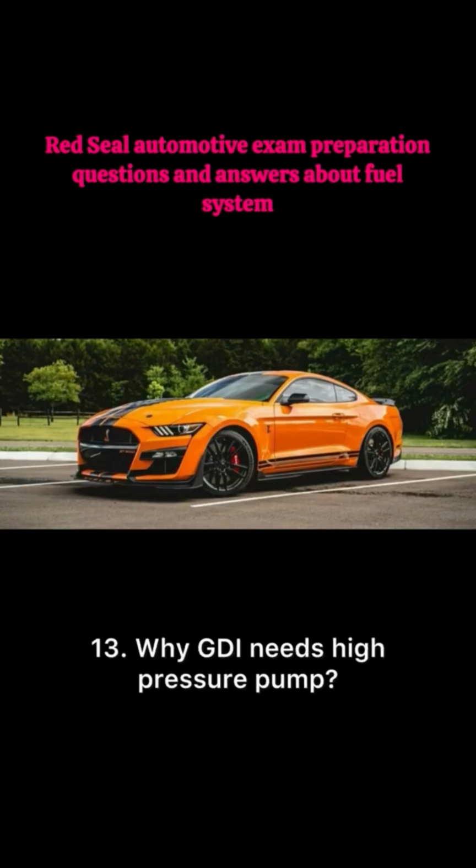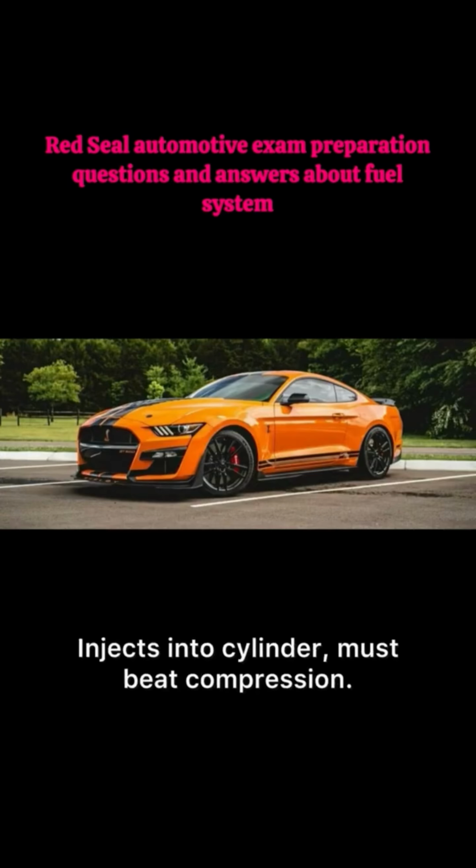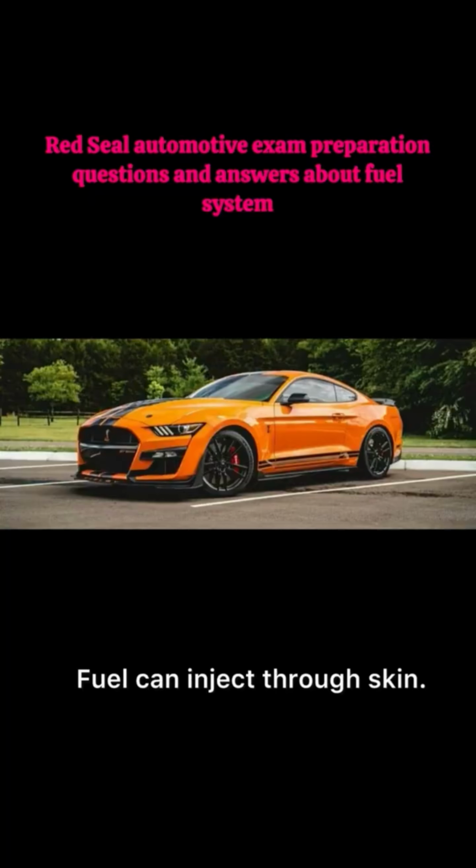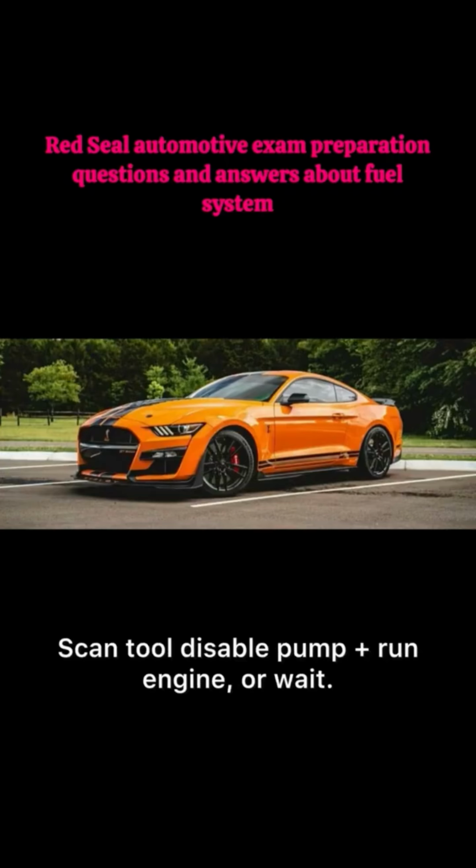13. Why GDI needs high pressure pump. Injects into cylinder, must beat compression. 14. Danger of opening GDI line without relieving pressure. Fuel can inject through skin. 15. How to relieve GDI pressure. Scan tool disable pump plus run engine, or wait.